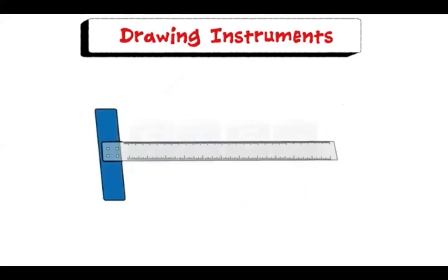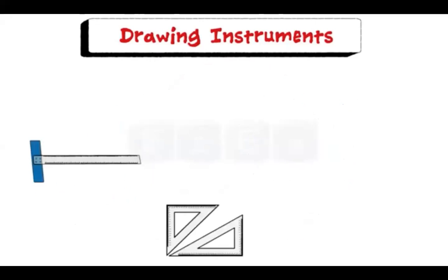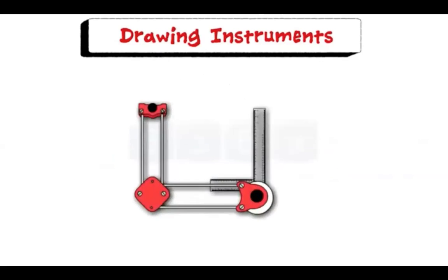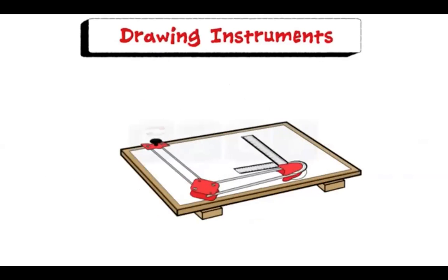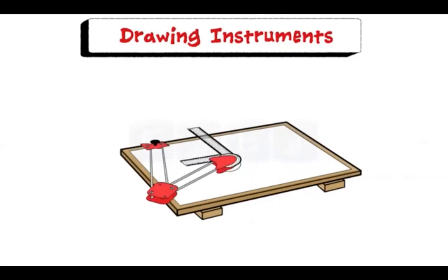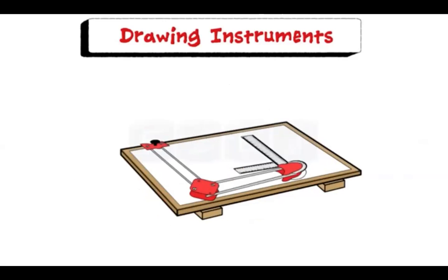The combination of a T-square, a set square, scales, and a protractor is a drafter. Its one end is clamped by means of a screw at the edge of the drawing board. The other end is adjustable. It has a scale which is at 90 degree and also has a protractor which can be rotated at certain angles. This scale can be moved anywhere we want within its limits.